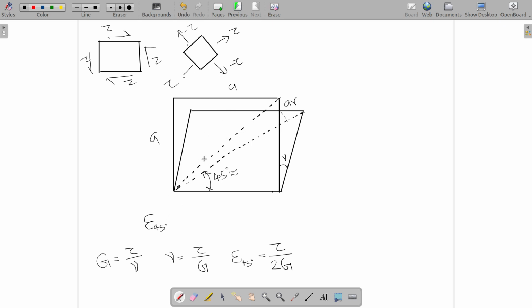Now this is actually equal to, from generalized Hooke's law, we know that this is equal to sigma 1 by E minus mu into sigma 2 by E. This is an expression you are familiar with.